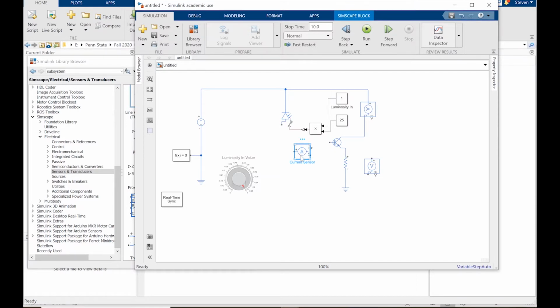These sensors operate just like a regular multimeter in real life. You measure current by passing the signal through the sensor, and you measure voltage across. So we want to make the current sensor part of the electrical circuit, passing the signal through to the positive and through to the base. Voltage also, just like real life, we measure across and in reference to one point, so I'm using the electrical ground as the same reference.